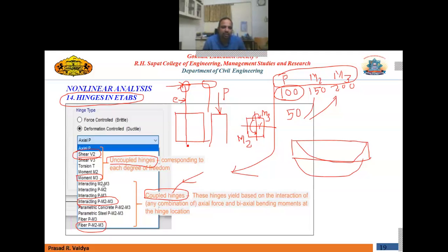Let's say this is your structure with certain geometry, and you know that the structure is stressed most at the peripheral level, right? So you can select the members at the periphery of the building, which will behave in a non-linear fashion, or in an inelastic way, and other members you can consider as elastic ones. That is also possible. So it is not compulsory that at all elements at all levels you should lump your inelasticity. Your model in that case will become complex, and the solution, it's an iterative process, will take considerable time, right? Okay, so that approach is also possible for nonlinear modeling.